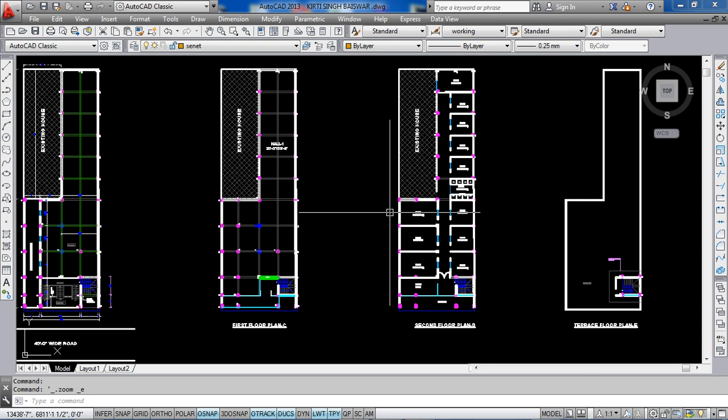We receive drawings which are either in feet and inches, or in mm or in meters. Preferably we give the STAAD input in meters and kilonewton, that is the SI system. So we prefer to export the plans which are in meters.